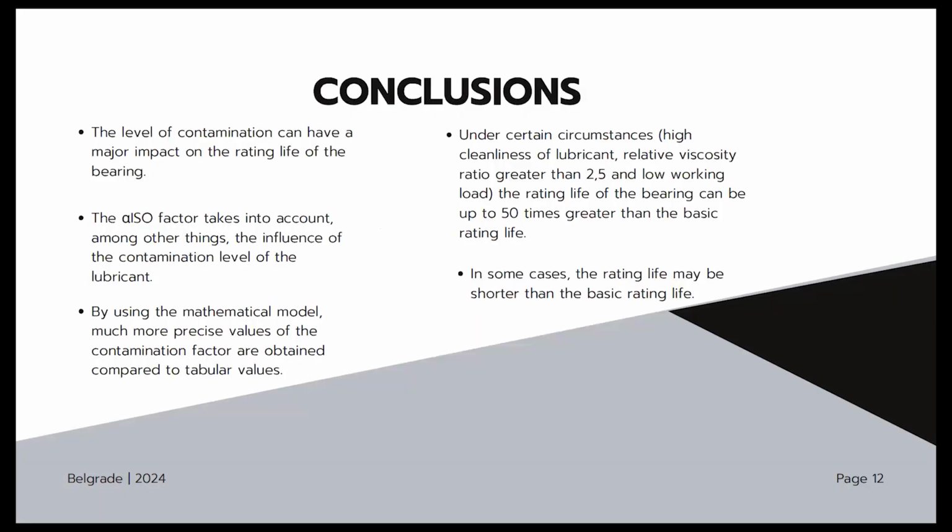And for the end, some conclusions. The level of contamination can have a great impact on the rating life of the bearing. Also, the contamination of oil is taken into account by the a ISO factor, and by using the mathematical model, we obtain much more precise values of the contamination factor than the table values.